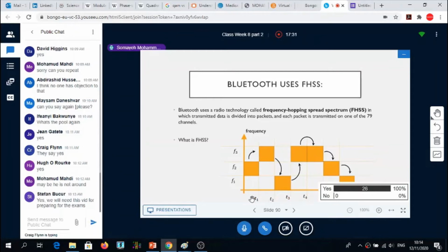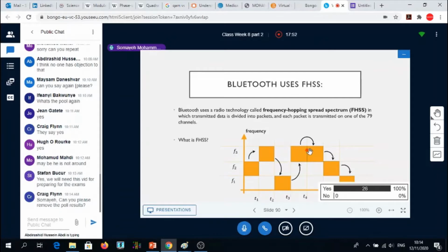The time when we are dividing the time duration and we are hopping from one frequency to another frequency, we are spreading the frequency spectrum in terms of the time and also frequency at the same time. And the hopping gives us ability to have a sequence which is very useful, and we use that sequence for providing security for our communication.